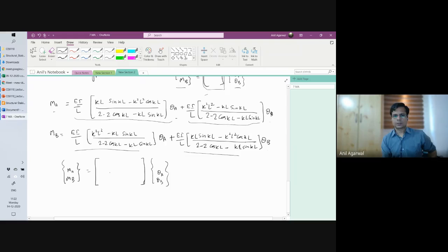Okay, we got SII, SIJ, SJI, SJJ. What are these? This is your SII because that is connecting MA with theta A. This is your SIJ. This is your SJI and this is your SJJ. Okay. So MA is equal to SII theta A plus SIJ theta B. And if you see, your SIJ and SJI values are same. But in fact, SII and SJJ values are also same. SII is same as SJJ. So not only is this a symmetric matrix, even SII is equal to SJJ, which makes sense.